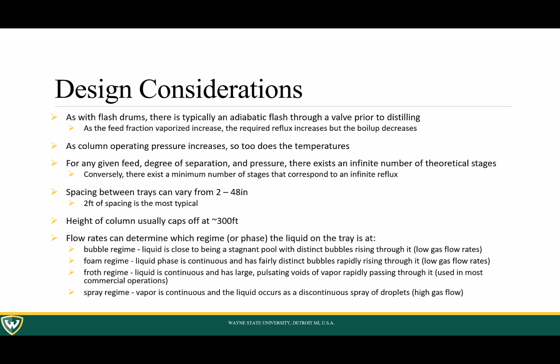When I say infinite reflux, let's draw a column here. You would likely draw a column, which I have in the next slide, with reflux. Remember, this is your reflux, your L0. When you completely close that off and you're sending all of it back into the column, that's when you have infinite reflux. Then there is also when you have an infinite number of theoretical stages, which we'll talk about on Monday.